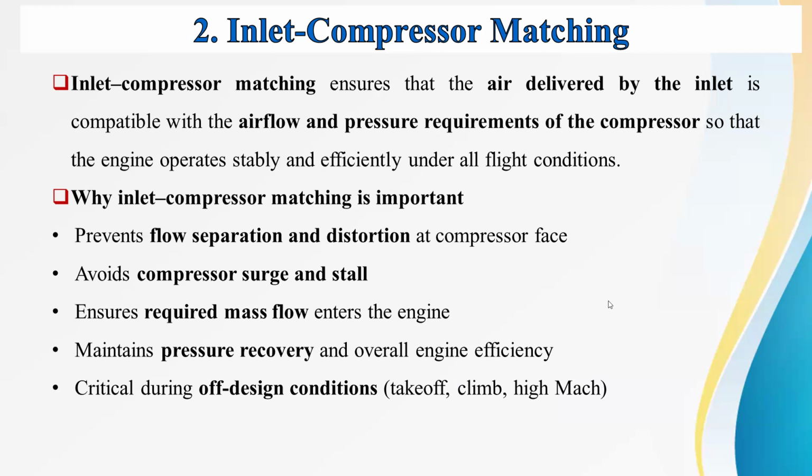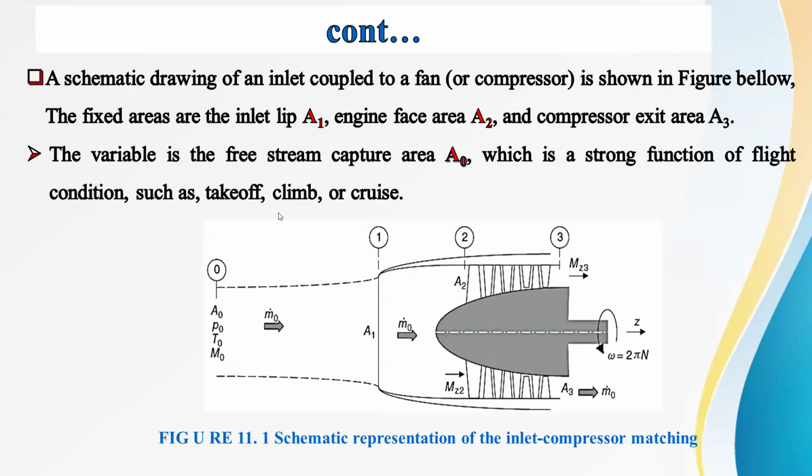And also, it is critical during off-design conditions, such as takeoff, climb, and cruising at high Mach number. So these are the reasons why we need to match inlet and compressor components.